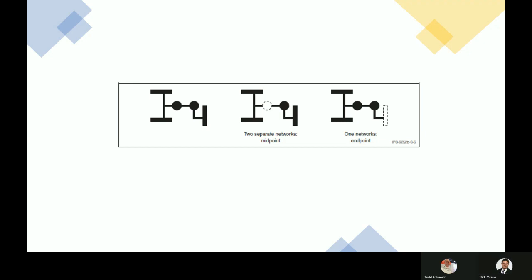Now, most people, if the pad was missing, if whatever mechanical process scraped away the pad and the trace was still there, you would still have a connection. There wouldn't be a problem. But when they went to solder the components on, or we went to final QC or QA and saw that missing pad, it would be a defect. But electrically, the board would still work.